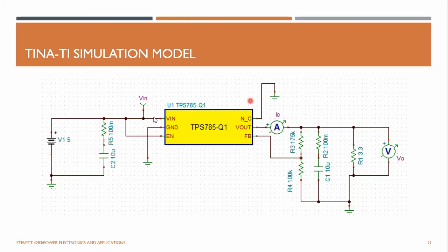Can the enable pin be used for switching to get the adjustable voltage? No, it is not a switch mode power supply. If you want to shut down, for example, if you want to save power, if you have a mobile phone at standby mode, when you're not using it, you just put it on your table, so you don't need to use your display or any other thing, right? So the internal control circuit will detect that your mobile phone is no longer used, and will just pull this enable down.